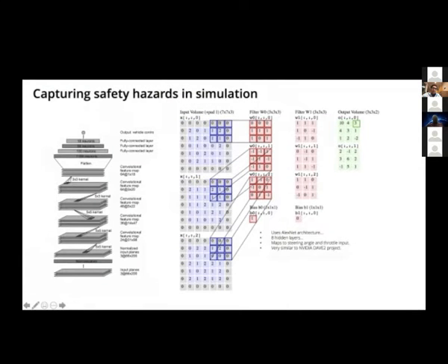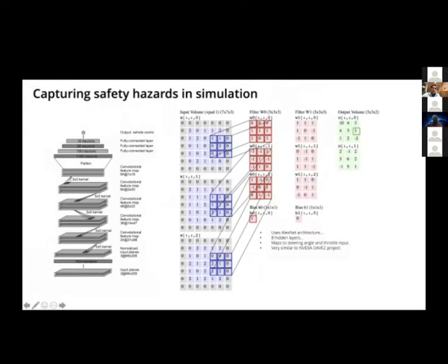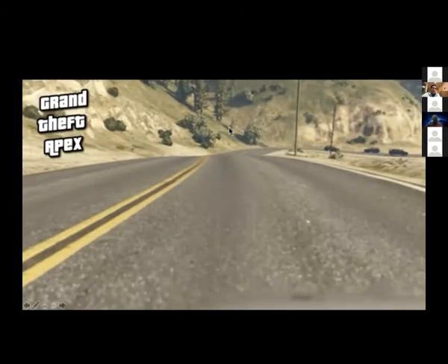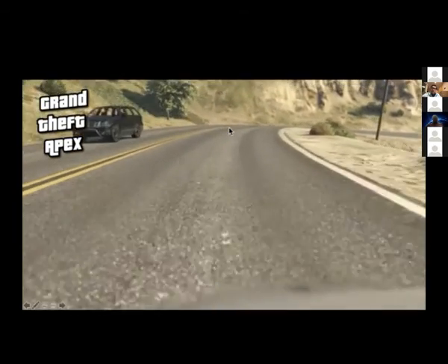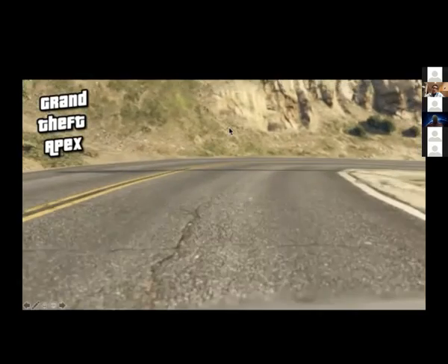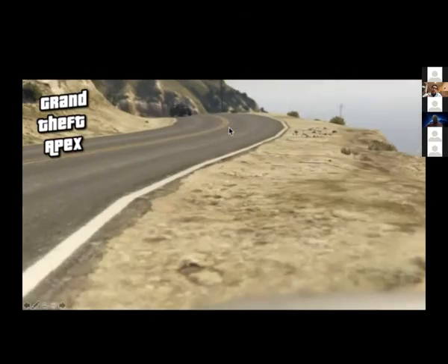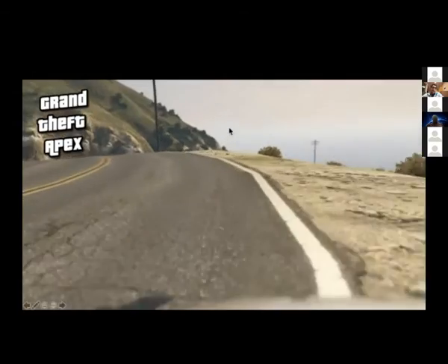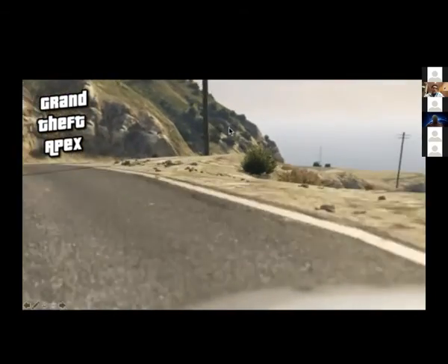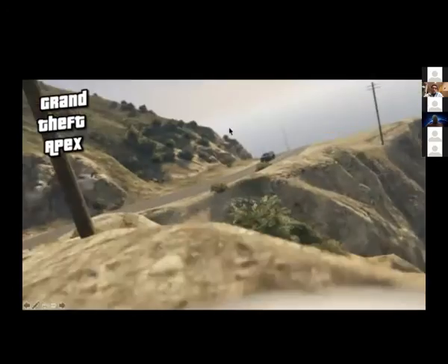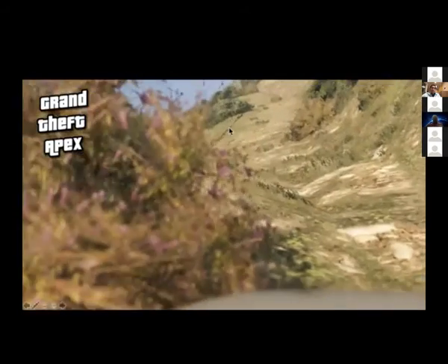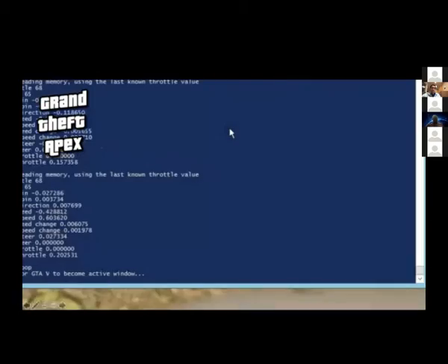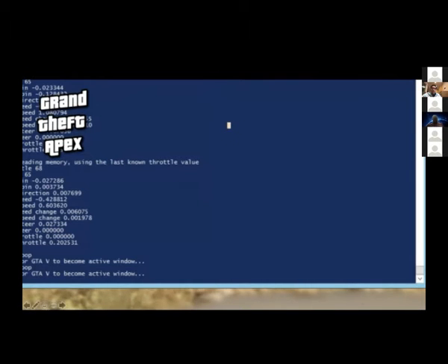As these vehicles started to switch to end-to-end driving, then we built a search engine essentially to look through hundreds of thousands of miles of these cars driving, and under the hood is all the formal verification and falsification techniques that are used to then capture when certain properties like loss of tracking or contact or time to collision violations are there to capture these situations. And so this is basically an example that is returned by the search engine to say, okay, here there is a failure, and now how do you go and fix this, right? So in reality, you don't get a blue screen. In reality, you have something more severe like that, right?